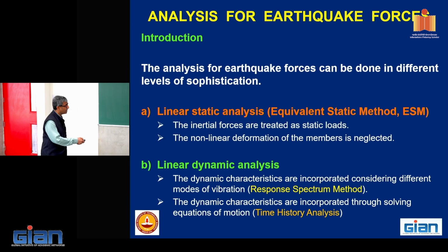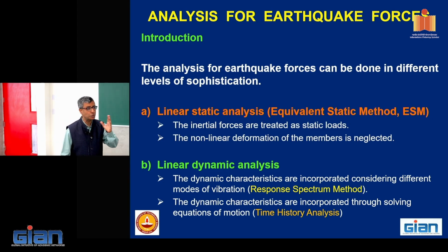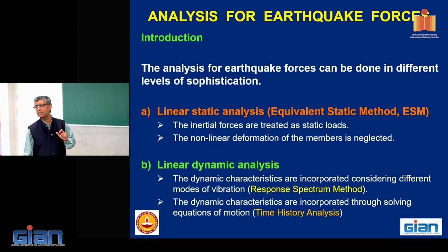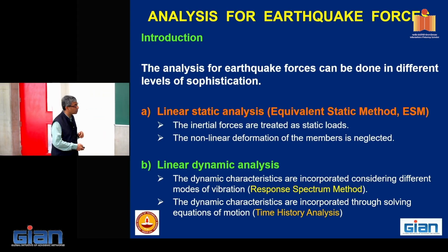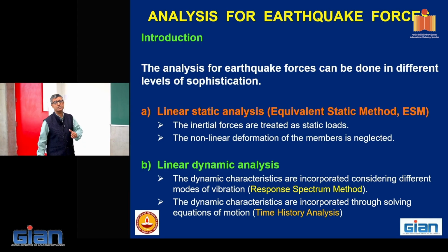The next level of analysis is the dynamic analysis. One method is called the response spectrum method, where we account for the different modes of vibration of a building, especially if a building is atypical, then we go for the response spectrum. Or there is a time history analysis, which is like solving a set of differential equations with respect to time.